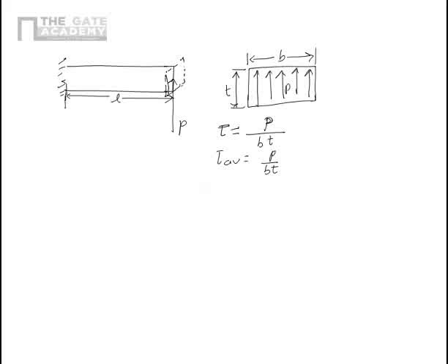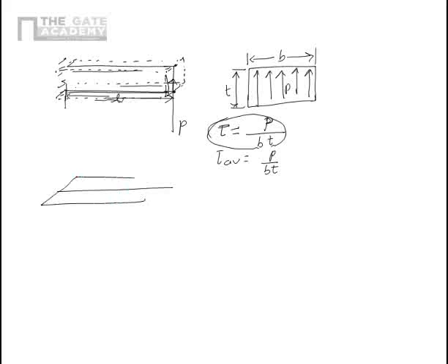See, the bottom face of the beam is like this. So this is the bottom face of the beam, and this is the top face of the beam. Both these faces, the bottom face and the top face, do not have any applied shear force. Hence, there the shear stress cannot be there. But seeing the formula, it seems that there is a shear stress there. That's not correct. So what happens is that the shear stress is actually 0 at this point and at this point. So if I just take the beam again and draw it in 3-dimensional view,